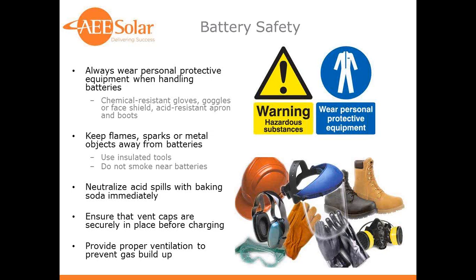Acid spills can be neutralized with baking soda, either baking soda powder just spread in, or you could have a baking soda solution in water to help neutralize acid spills. Make sure the vent caps are securely in place before charging. The vent caps will prevent a lot of acid mist from escaping from the battery while it's charging, which can make a mess and cause a lot of corrosion of cables and whatnot.